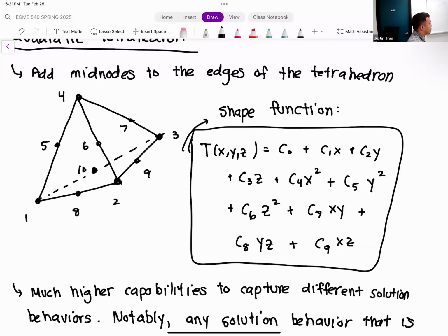to maintain this perfect shape? And definitely not. So there are going to be situations, especially if you're meshing a more complex geometry, where these tetrahedrons have to be skewed and squished. Maybe one side is much longer than the other one. So that happens actually very commonly.